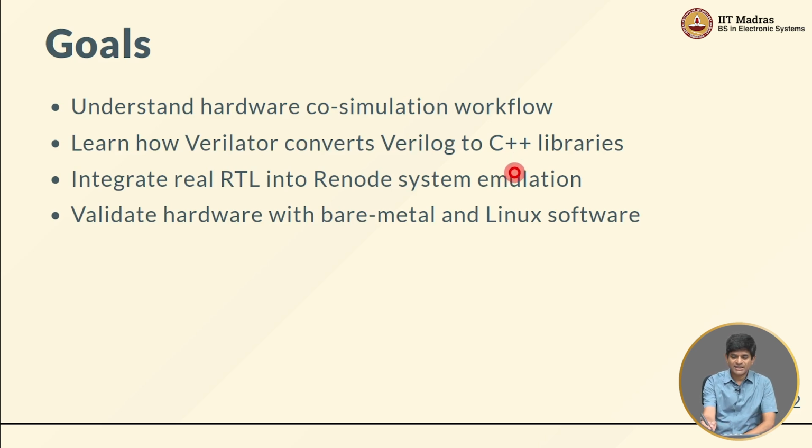And what that means is that because it is able to compile into a set of C++ files and therefore create a library that is in software, we can then integrate that into the Renode system and do an emulation where one part of the Renode platform that we are building is going to be a co-simulated peripheral. Whenever the AXI bus, for example, tries to communicate with that device, Renode has the ability to go out there, activate that peripheral, get the data back from there, and then feed that back into the emulation and continue on its way.